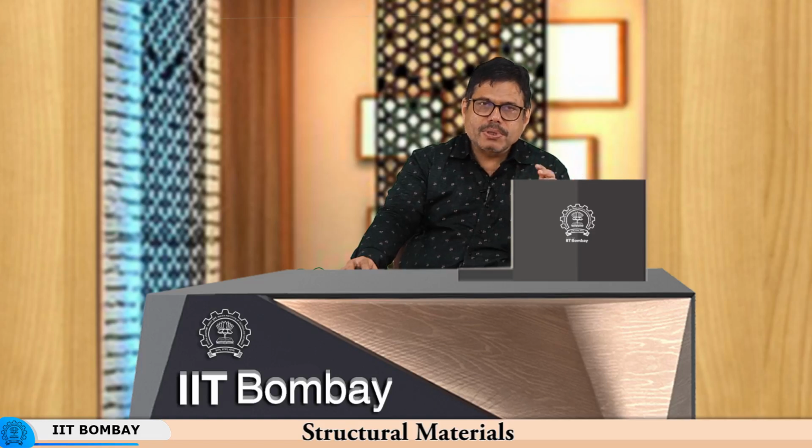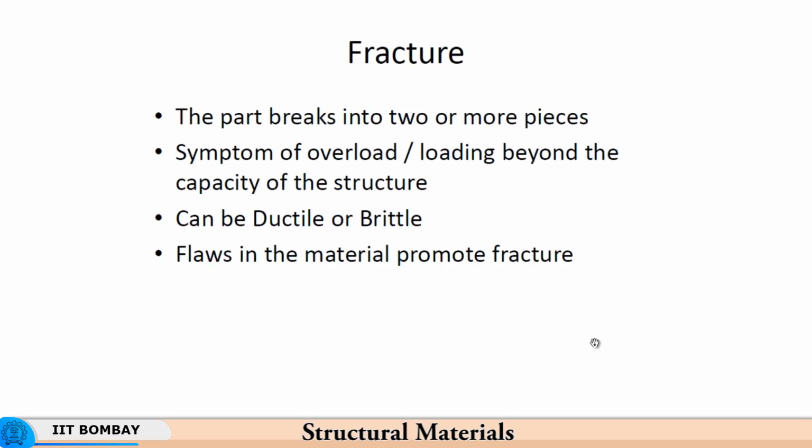And so, although structurally the part is integral and there is apparently no damage, you would still like to change the part and avoid any possibility of large scale disaster. For critical applications you do not let the fracture take place. The minute a defect arises in the part, you just replace the part. In fact, testing is often done for such critical parts, where they monitor generation and propagation of defects, and when the defect tends to propagate, the life of the part is said to be over.